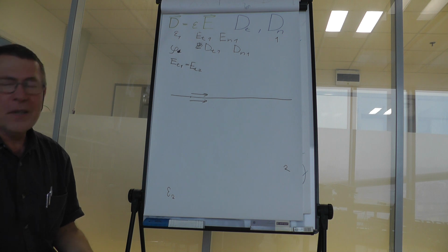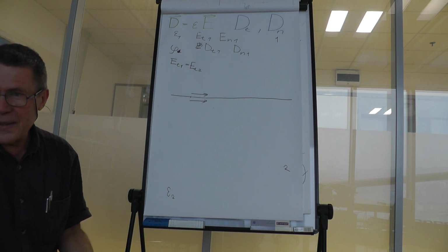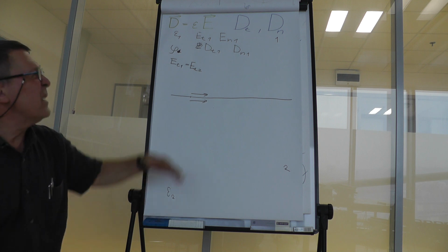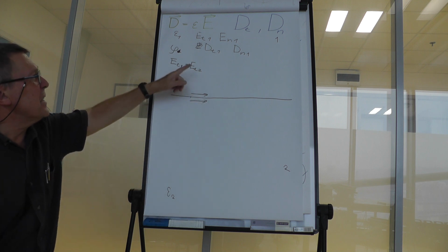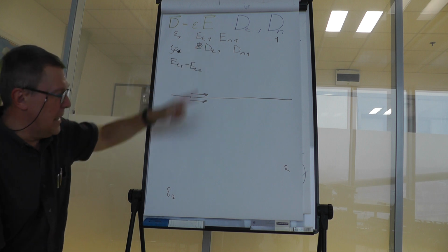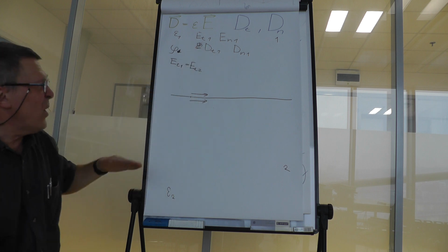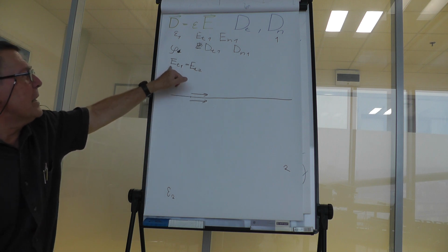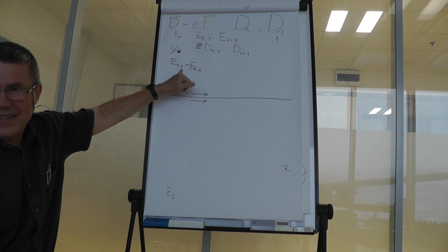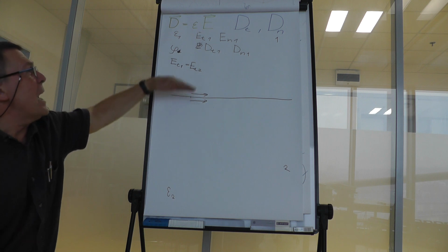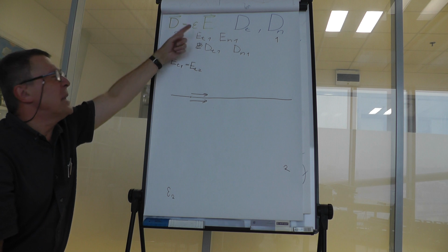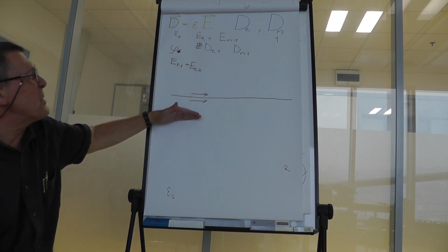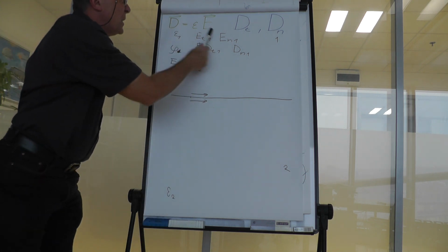Now, if this is true, we can also tell something about flux densities over and under, that is D tangential 1 and D tangential 2, because both of them are given as a product of the tangential field strength, which is upstairs multiplied by the permittivity epsilon 1 and downstairs multiplied by the permittivity epsilon 2, according to this equation.